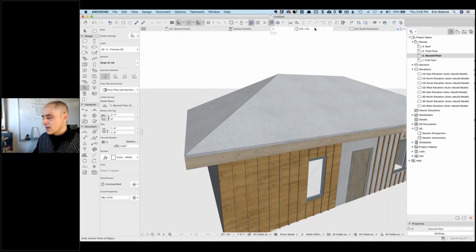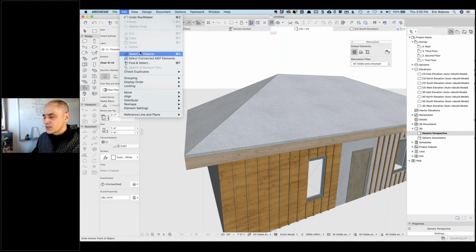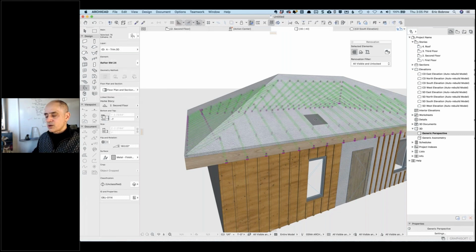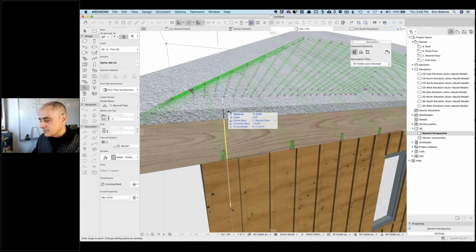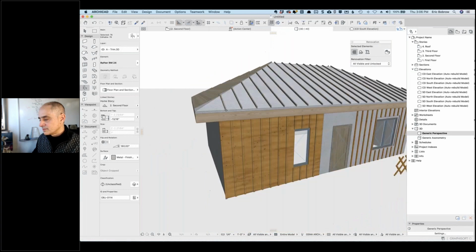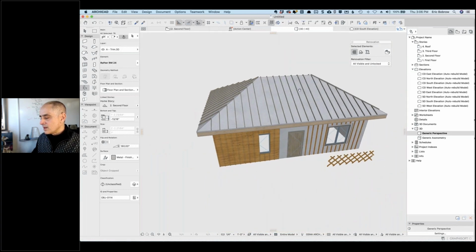Go here. Now, I go to 3D, I don't see it. These are objects, so I've got the object tool active. I go and select all objects, and you'll see there's a whole bunch of things that are buried, like framing would be. They are down here. I'm just going to drag them up to there. Okay.